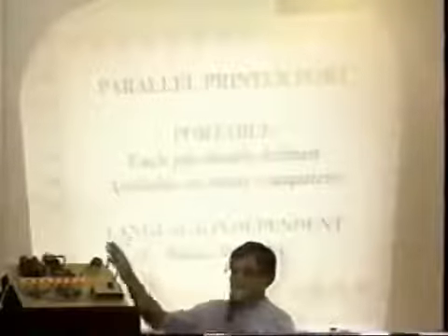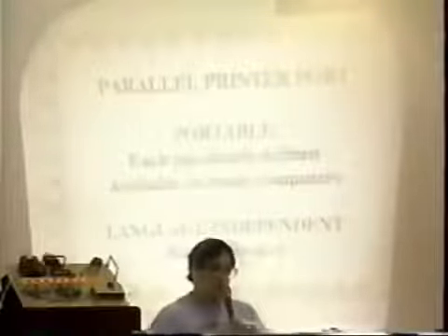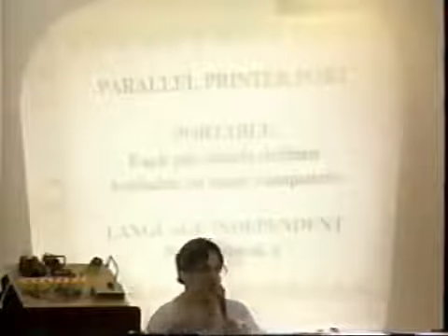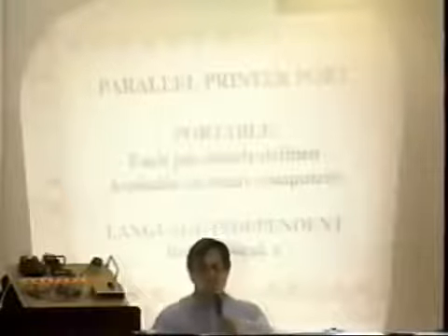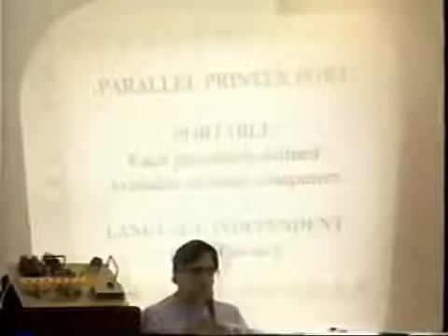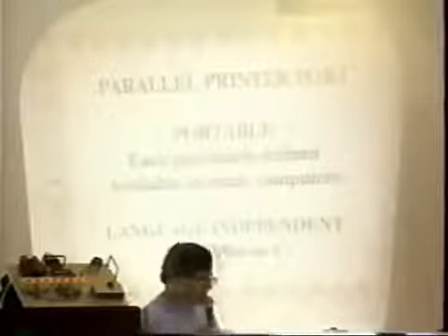There's a story I remember, somebody wrote in a computer magazine that they went into a store and said, I need a serial cable to go from this printer to this computer. And he said, certainly, sir, you need a 3X21. And he went to this board, and there were 50 serial cables, all different for different hookups. And he said, now, if it isn't up there, we'll make you one. And the thing is that serial is not standard. Everybody has their own way. Each company uses their own way of connecting A to B. Sometimes they call it a DTE. One's a computer and the other's a terminal, and I don't know. They got a whole bunch of standards. So we can't even talk the same with the serial.